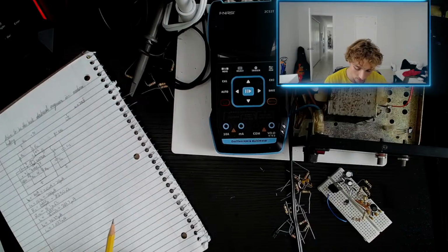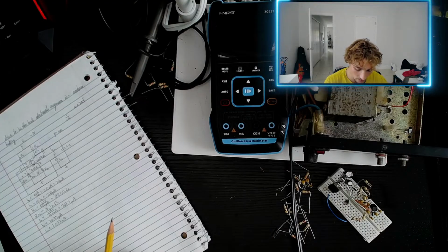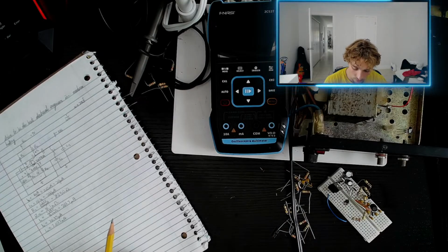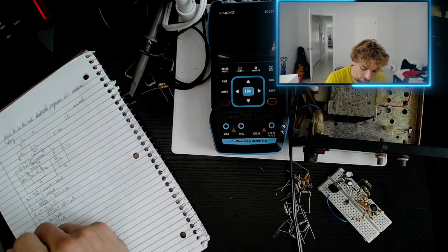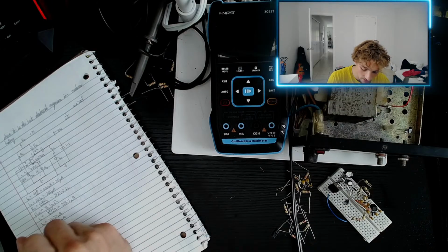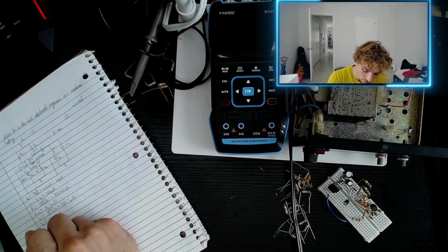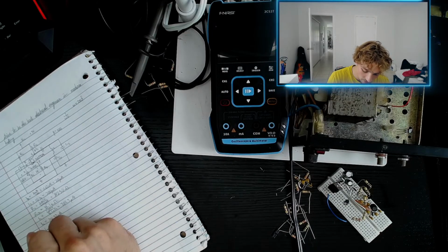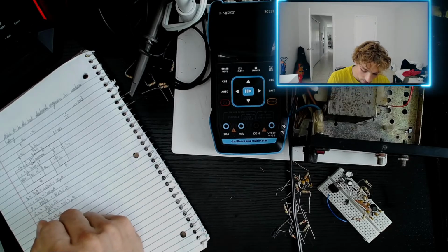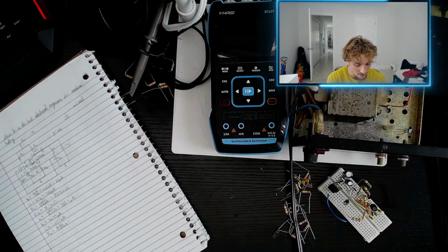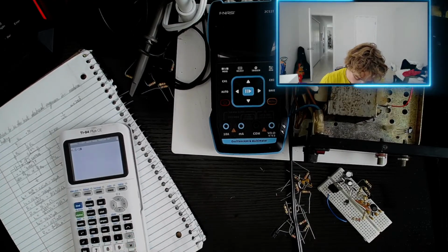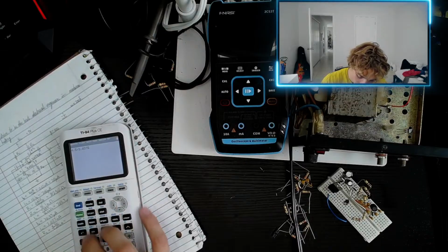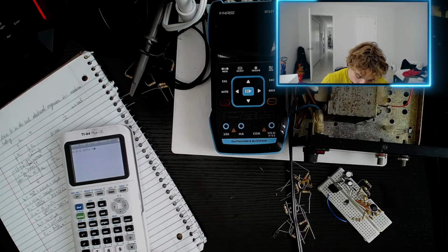We know the voltage across the collector resistor, which will be half of 9 volts, 4.5. Therefore, we can find the value of RC: 4.5 volts divided by 2.037 milliamps, which is 4.5 divided by 2.037 times 10 to the negative 3.